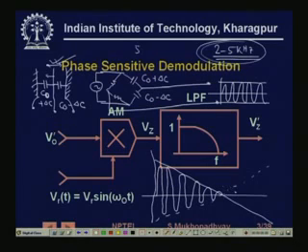And here there will actually be a phase inversion, because the modulating signal is negative here, right. Here the modulating signal, the motion, is positive, and here the motion is negative. So, there will be a phase inversion here, which will be very difficult to detect. These waves will look very similar if you see them in the CRO.